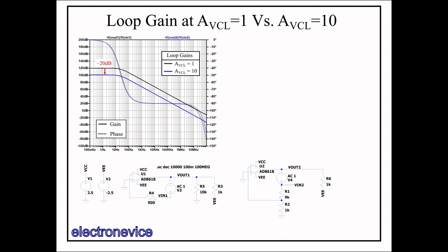The phase deviations toward the higher frequencies are likely due to non-idealities in the input and output impedance of the op-amps, though it's difficult to determine the exact cause. But these non-idealities are only showing small changes in the phase, and only after the 0 dB gain point, and so they don't affect the analysis much.